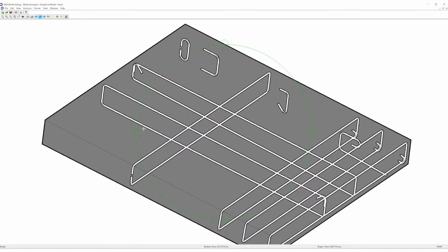The algorithm has a serious dependency on the Revit file version, and we initially started with 2023 because it provides a cache that significantly helps to work with it. Next, we'll implement correct update of rebars in files below 2023. When this is finished, we will draw a rebar for all files beginning from version 2015.